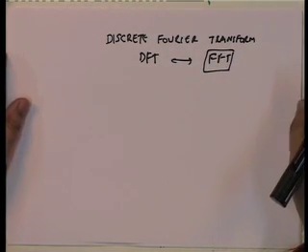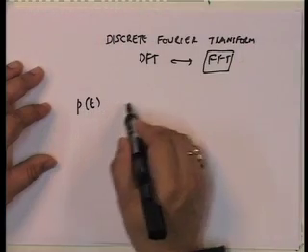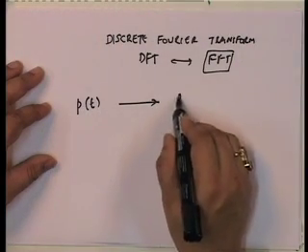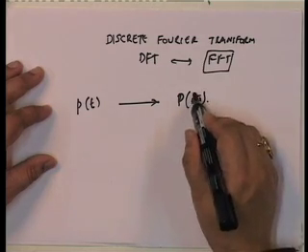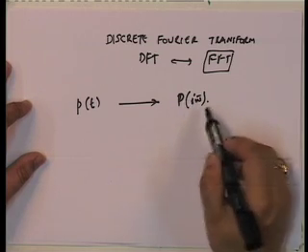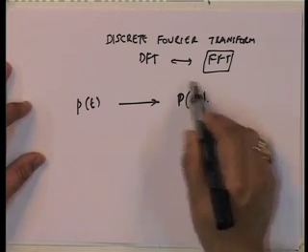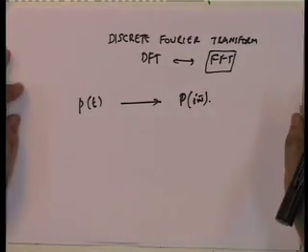Everybody would have heard today that, oh, I did an FFT of a signal. Well, what is an FFT of a signal? It is actually a Fourier transform. I have taken the load P(t) and transferred it into the frequency domain. And remember, I wrote P(i omega) just to show that P is a complex function of omega bar. That is all I am trying to show.